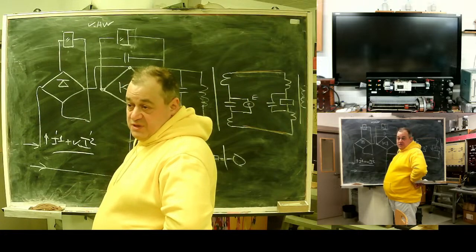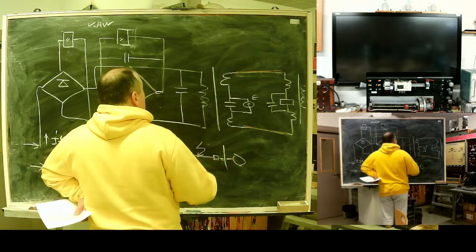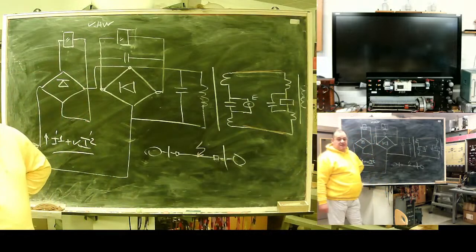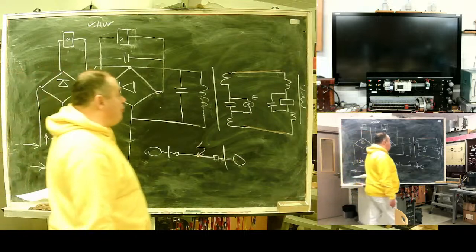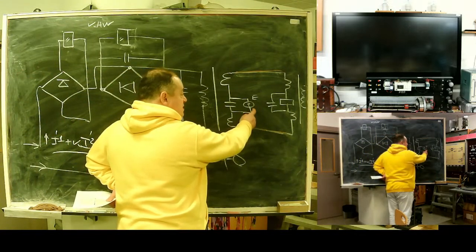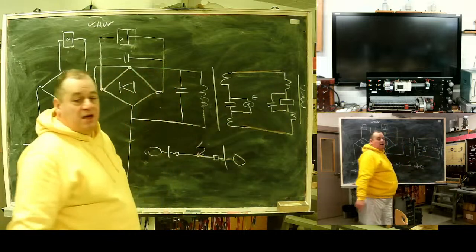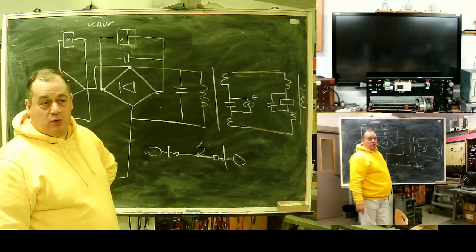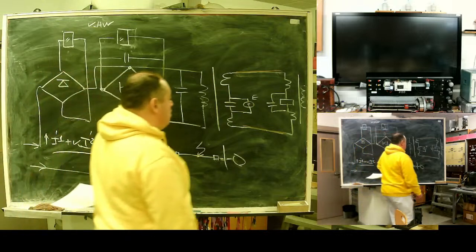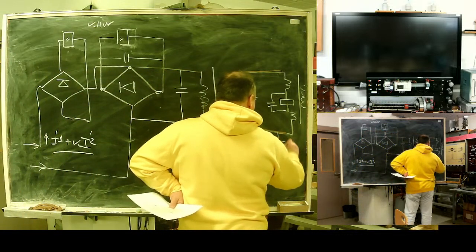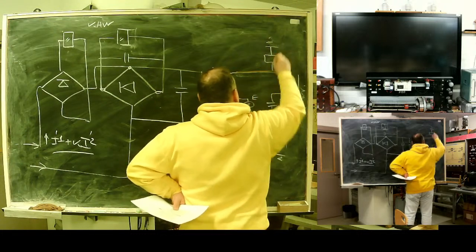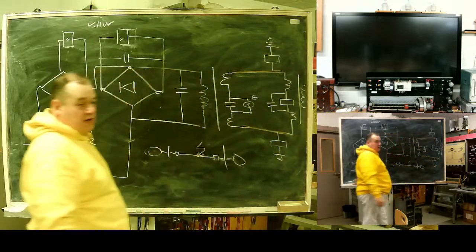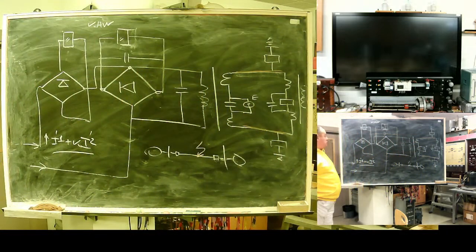If this current loop is disturbed... first, our information circulates as a 100 Hertz current. The DC component here is a power supply and DC relay. The DC component allows checking line integrity. Also, it had 2 insulation control relays, voltage relays, to check line insulation against ground.